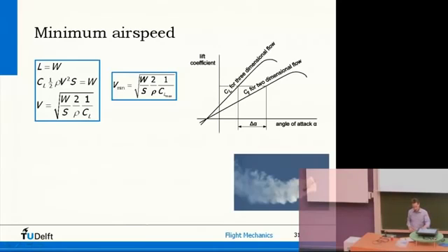And this picture here is a nice example. What you can see there is the aircraft is actually quite steep. It's flying horizontally, and you can see from all the flow around the wing that the aircraft is in a more or less stalled condition. Now this aircraft is basically cheating because it's an aerobatic aircraft, and this propeller can create a lot of thrust. So it's more or less hanging on its propeller.